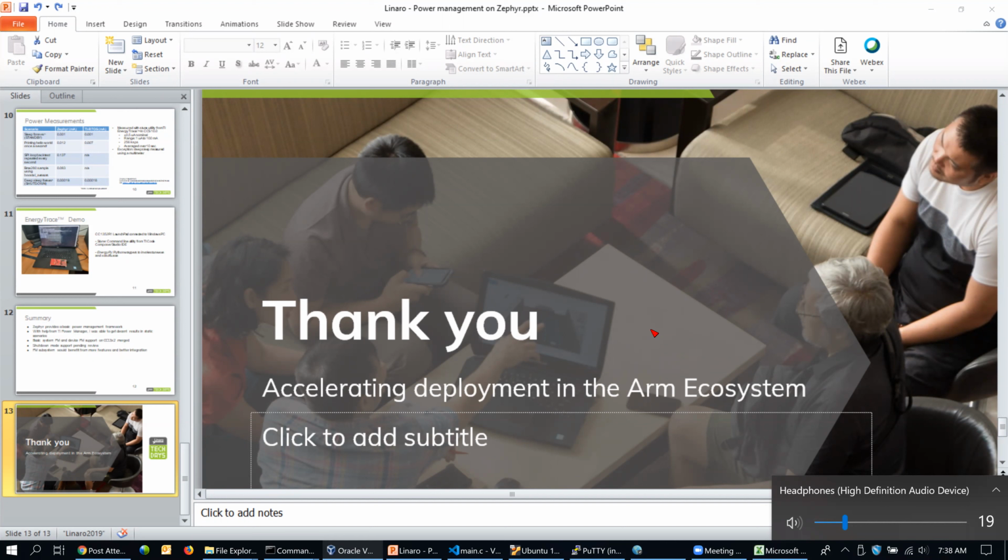I guess I was curious, and this is just me putting my let's-make-things-complicated hat on. Is there any sort of timeout with a driver? Let's say there's a system event where I say enter a specific sleep mode, and then that will send a callback to other drivers. But do you have to get a response back, or is there some sort of timeout, like if a driver just doesn't respect something and doesn't go into low power mode?